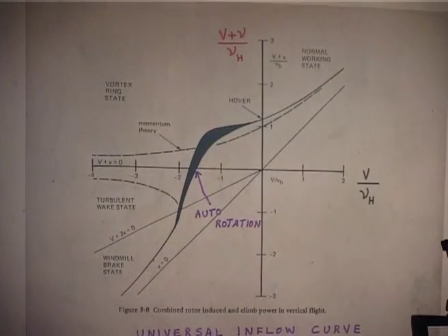That is because usually we do not take the tail rotor power. In practical problems, you have power taken by the tail rotor also. Those are not included when I write the power; it is only the main rotor, that is number one. We neglect swirl effects. Even though there is a small percentage, we neglect that. Non-uniform inflow, these are all calculated based on what? Uniform inflow. Non-uniform inflow may change the power, right. And then swirl, then there can be transmission losses.